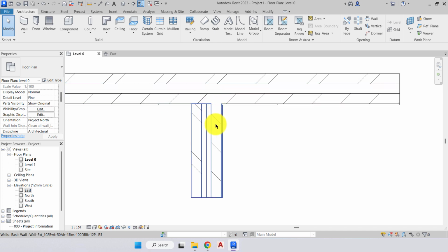The reason that the core will look for another core is its structural integrity. So again, the structure of this blockwork attached to the structure of this blockwork, because that is the structure of our building. Everything else is simply just a facing brick. It's our cavity or insulation. So they are not connecting.